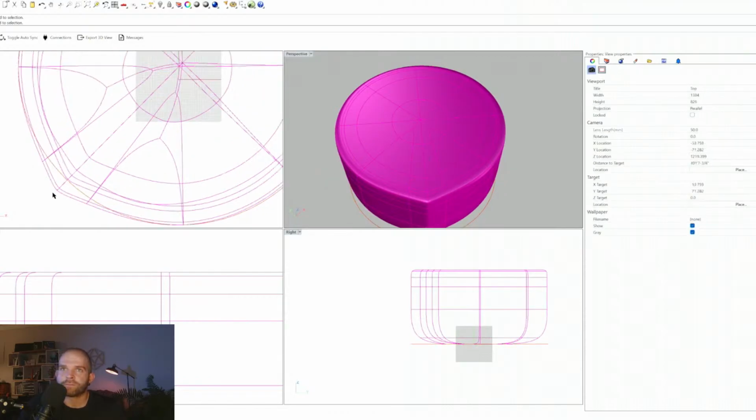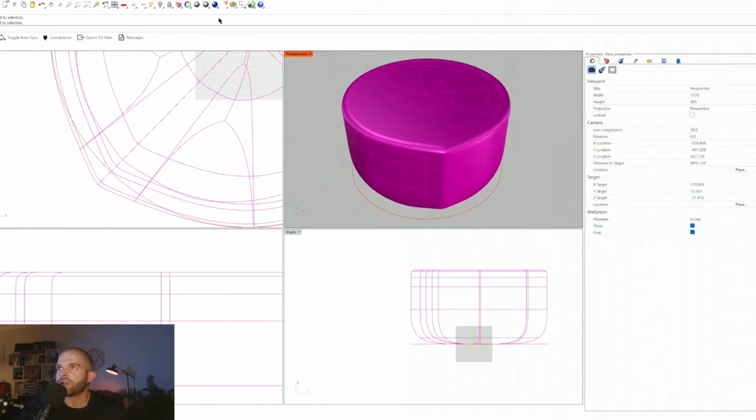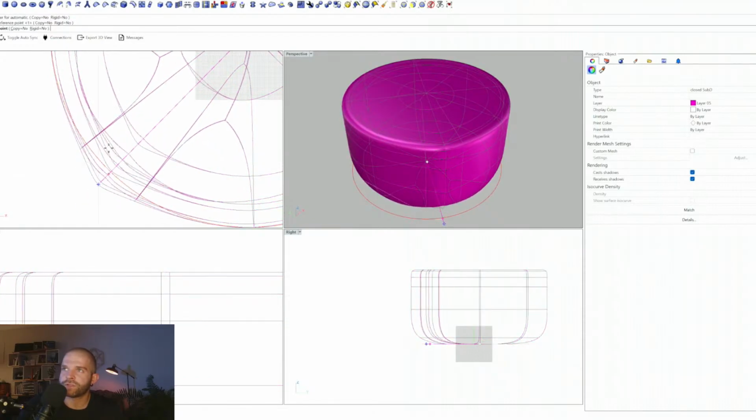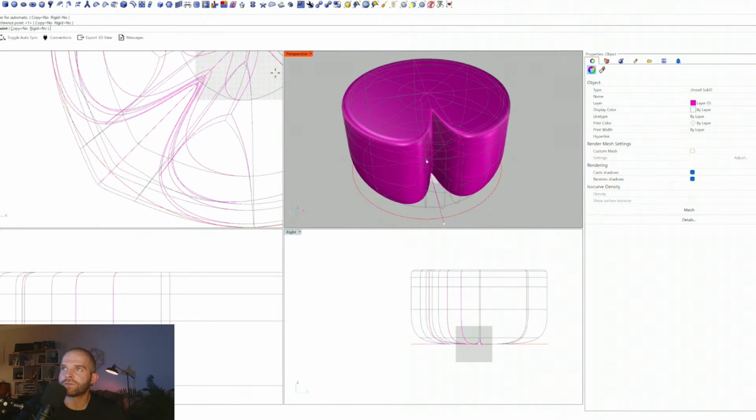Okay. So now I can grab that whole edge by selecting it here with our select edge loop. That's going to be our best friend. Do a scale 1D of that edge from the center point, right? Turn off all my snaps because I just want to select the edge here, projecting from the vertex. Okay, there we go. So right now I can just pull this edge in and out, right?